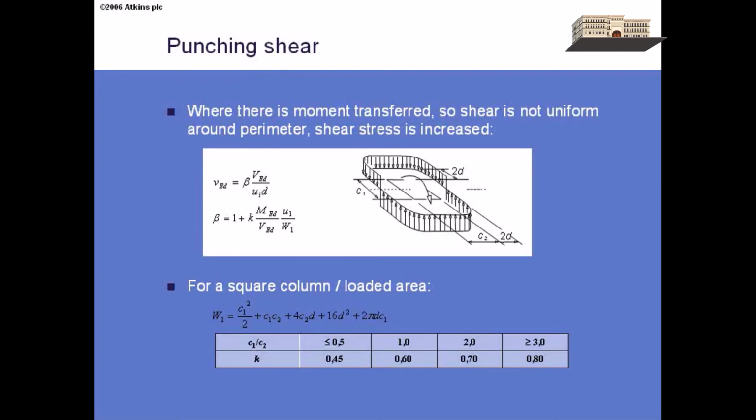So there's an extra term here, beta, which basically looks at the bending moment that you've actually got, and it transmits, it turns that into a plastic bending distribution of shear force around the perimeter that you're checking. And that up and down force from bending adds on directly to the shear force that you get from the vertical load. And so it's all done with a plastic stress block. We haven't done that before.